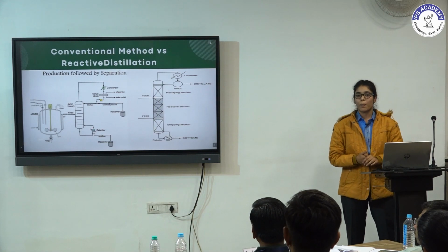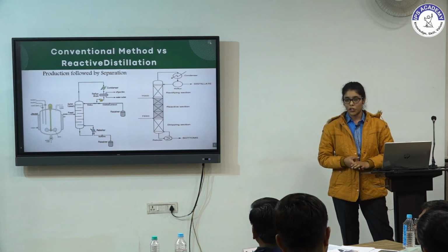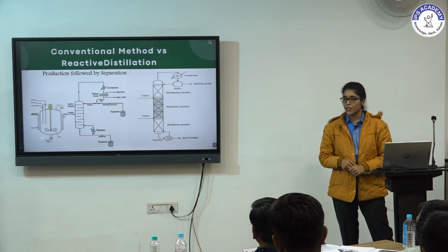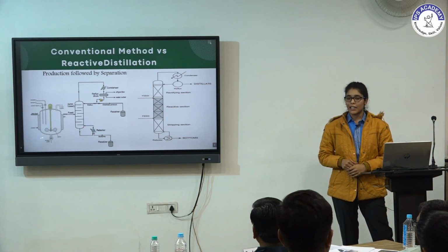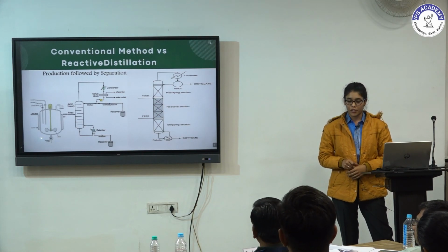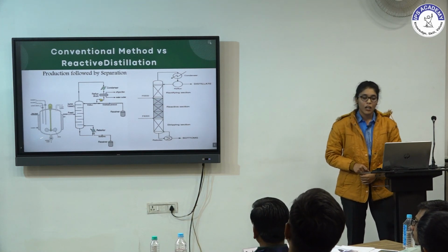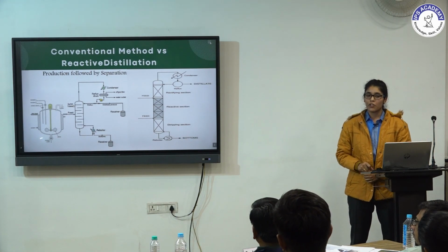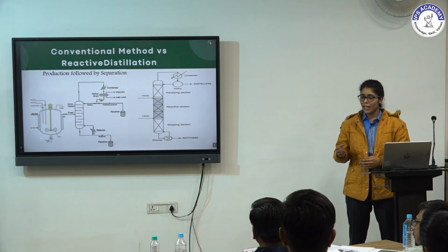But here we have to produce the biodiesel with the process of transesterification, and it demands a basic catalyst such as NaOH. But here we have chosen the solid heterogeneous catalyst, that is Amberlyst. The lifespan of Amberlyst is very good, and it doesn't require any regeneration over many years.